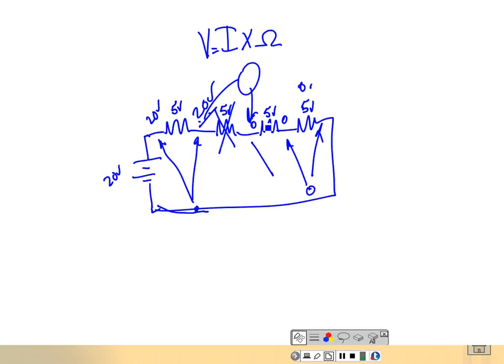Now I measure a fuse with an ohm meter. How many ohms should a fuse have with an ohm meter? Should have almost none, right? So if you check a fuse with an ohm meter, it should measure pretty close to 0 ohms. I'll put that on the test: I measure 0 ohms across a fuse. For some reason, we've got in our mind that 0 is bad. I'll put that on the test.